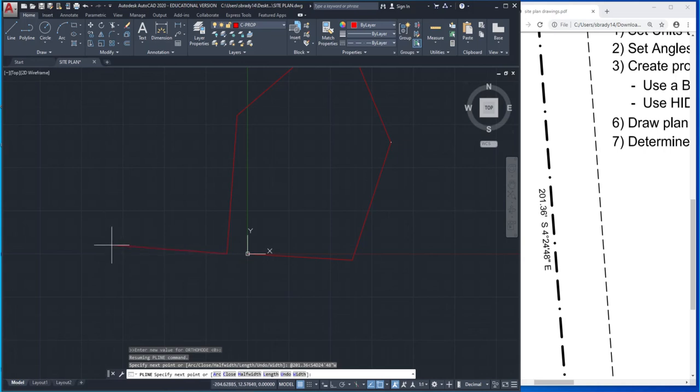Let me talk about a few polyline options that we have. Polyline is an interesting little tool. I can, number one, have my lines all continuous, which is great. The other thing that is really great about a polyline is that if I make a mistake like this, I don't have to hit escape and hit delete. Do you notice we have some options down here? I have an undo option. So if I click undo, it just undoes that last mistake that I made. Okay, so I'm going to redo it.